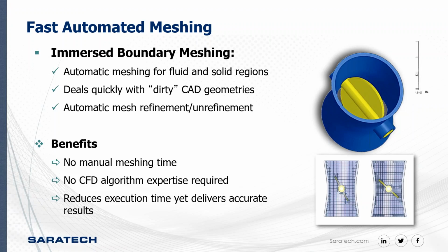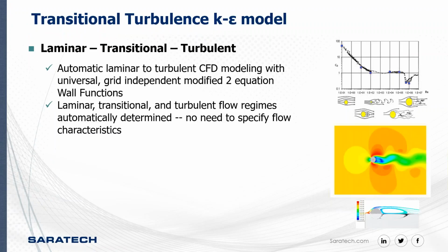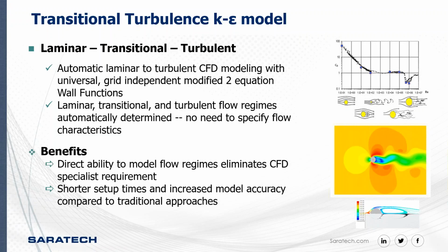Turbulence modeling is also something that we handle very nicely. We've got a full laminar, transitional, and fully turbulent flow regime model within Flow EFD. And again, it's largely automatic, so you don't really need to know what sort of flow is going to be happening inside of your electronics. Is it going to be natural convection? Is it going to be forced convection? Are you going to get boundary layer growth in the fins of your heatsink, for example? So you really don't have to be an expert to use our tool.